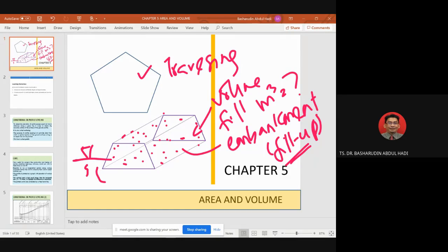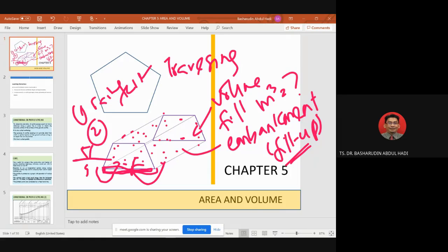Sometimes the water level can also go to your sub base. So what we do, we put here a waterproofing layer, either using a geotextile layer or another method recommended by the engineer, right? And the water comes from two sources in Malaysia. One is rainfall, and another one is groundwater. Sometimes the rainfall goes down and penetrates to a certain level, and then it goes back up to here. So for example, you have rain here, and this one is penetration. Some goes straight down, some goes back to the base of the embankment.